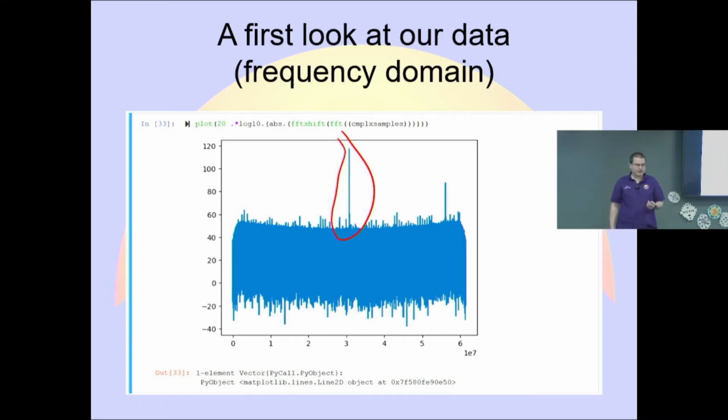So what we do in the SDR world often is we do something called offset tuning. If you're using one of those GUIs and you're trying to listen to a signal, you probably don't want to tune your SDR right at the signal you want to listen to, because there's this artifact there. Tune it a little bit off to the edge, and then in software do a shift and listen to the signal you actually want.